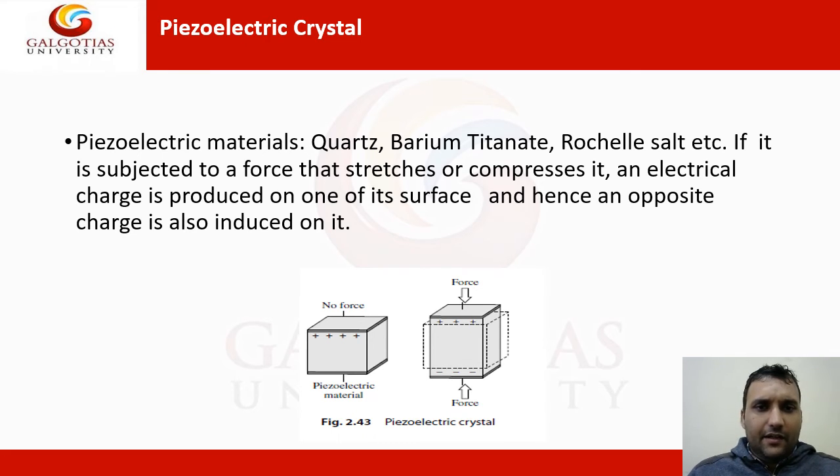Next is the piezoelectric crystals. The piezoelectric materials are quartz, barium, rock salt, etc. If it is subjected to a force that stretches or compresses it, an electrical charge is produced on one of its surfaces, and hence an opposite charge is also induced on it. This is piezoelectric material. When there is no force, no charge is produced. When there is a force, so the compression force is working here, some charge is produced or induced in this system.